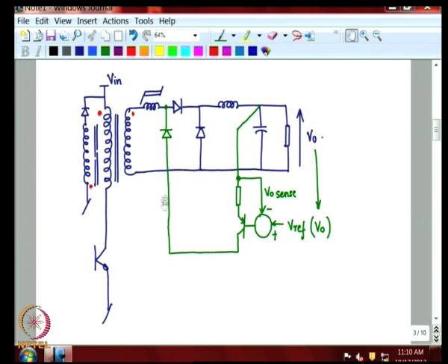So, once the current flow here reduces, the resetting action on this inductor is reduced and the flux reduces at a slower rate. And therefore, by the time the end of the period comes, the flux would have reset to a higher value than before.